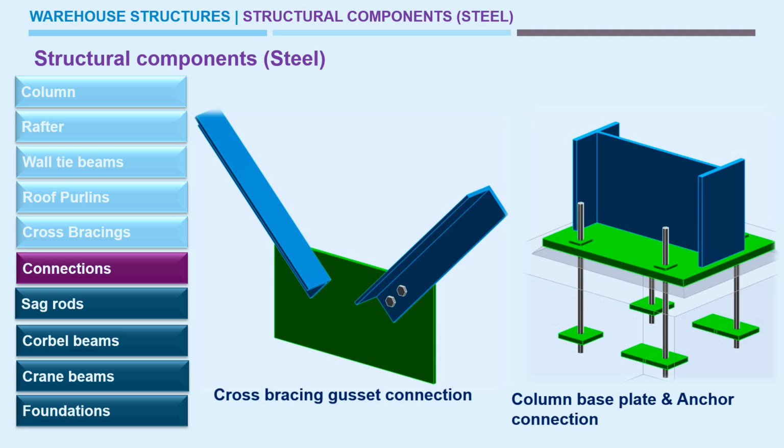Also, if there is any eccentric loading from the column, say the column is placed at a distance away from the base plate center line, then it will cause an eccentric moment also. So that moment is also considered while designing base plate connections. The base plate is designed based upon the acting force and the resisting force from the concrete pedestal.